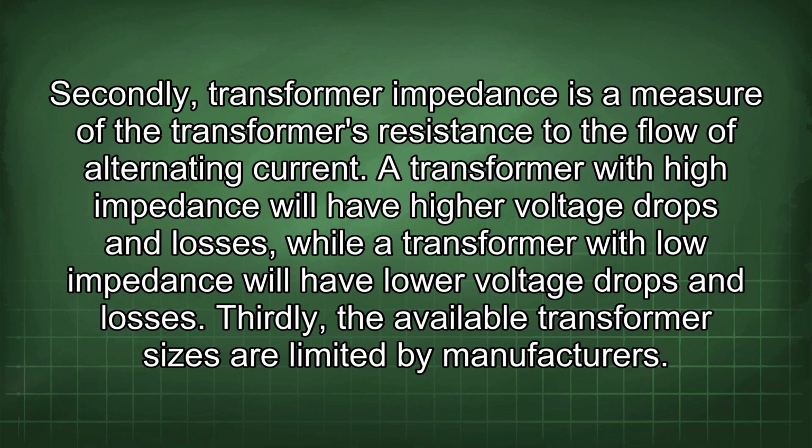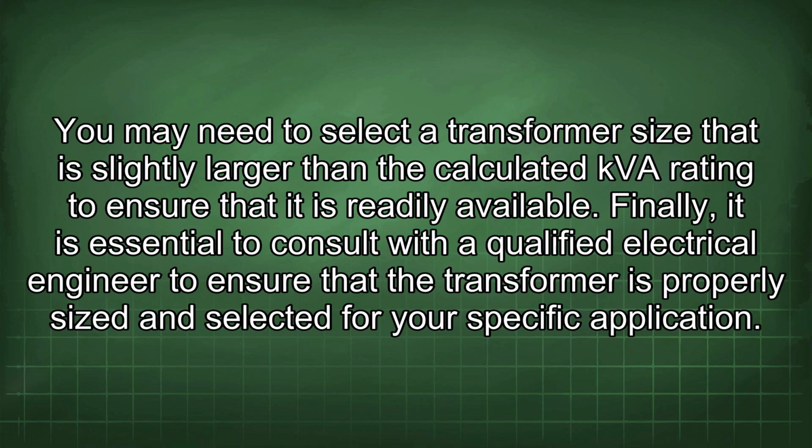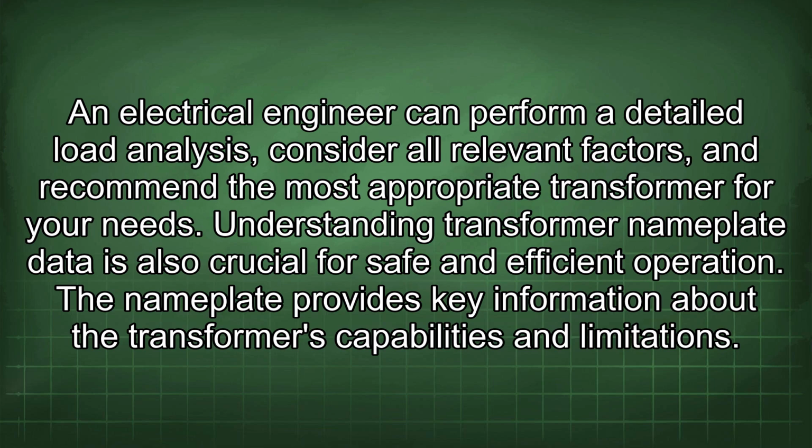Thirdly, the available transformer sizes are limited by manufacturers. You may need to select a transformer size that is slightly larger than the calculated KVA rating to ensure that it is readily available. Finally, it is essential to consult with a qualified electrical engineer to ensure that the transformer is properly sized and selected for your specific application. An electrical engineer can perform a detailed load analysis, consider all relevant factors, and recommend the most appropriate transformer for your needs. Understanding transformer nameplate data is also crucial for safe and efficient operation.